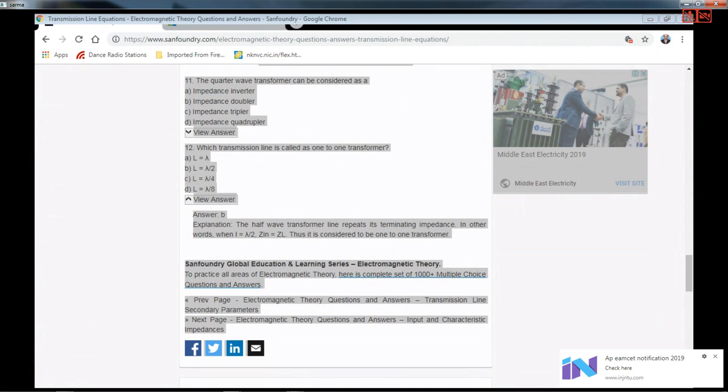Okay, and if you want the other way, that is, what is gamma in terms of VSWR, the second equation is going to help us. So by doing componendo and dividendo, you can see that mod gamma is given as S minus 1 by S plus 1. So the gamma and S relationship is indicated. Please remember, whenever we are talking of S, it is the magnitude of the reflection coefficient that only matters. The phase of the reflection coefficient has no direct relationship with VSWR and other calculations.